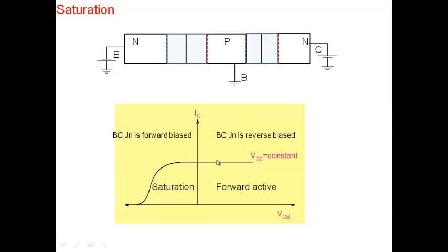So what we note here, and we have seen that earlier, is that collector current in forward active is almost independent of VCB here, collector base voltage. It doesn't matter whether you apply small or large, to the first order approximation. It doesn't matter what VCB is. When you go and forward bias the base collector junction, which means you enter into saturation, collector current remains constant for a while, that you see here, and then begins to drop. And can become 0, and if you push it further, will go into even negative value. Okay, so this is the behavior.